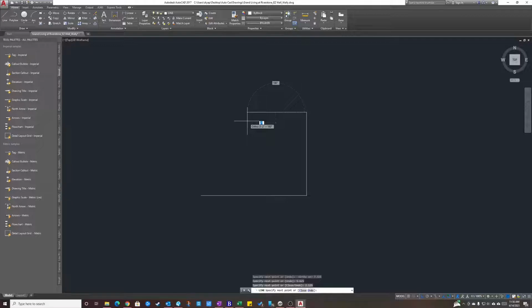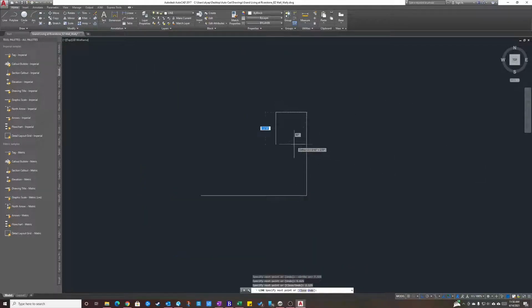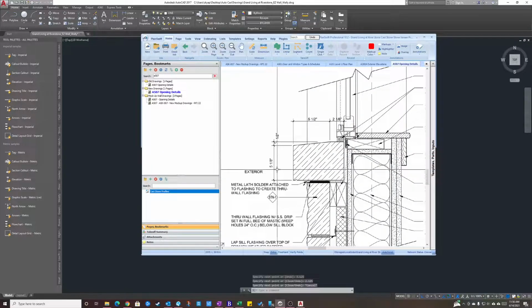Now, we have a little bit of a conundrum. The next line, the 5 1/2 inch that we have to draw to complete our shape, is sloped. So how do we do that? Well, I'll show you. It's sloped by half an inch. So what we're going to do essentially is hit escape, so we have a partial shape. The dimension in the front is 5 1/8.